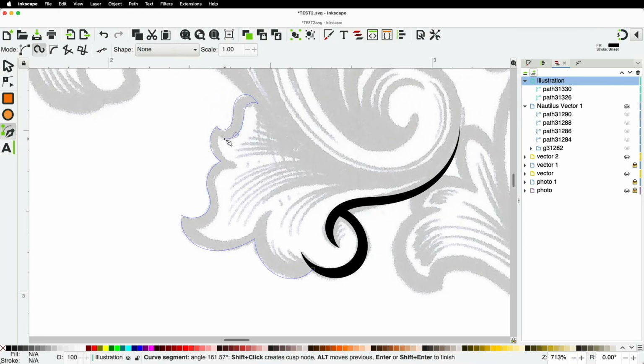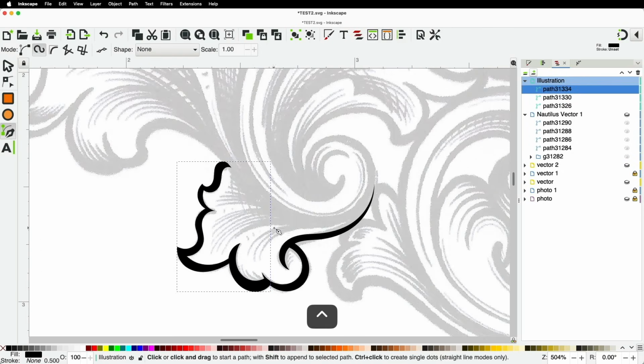The advantage to doing this also is you can vary your line thickness here. When you have engraved lines that are all the same width, the design just doesn't have any life. So I'm going to hold down the Shift key here to get a sharp corner. Shift key. Sometimes when you drag out, you can see whether you need an extra point or not, or if it's going to make the shape you want. I'm going to hold the Shift key, select the next one. Okay, this is all it takes to trace your design. And if you were to send this to a laser machine, it would burn these shapes just as you see it here. Now, this is good.